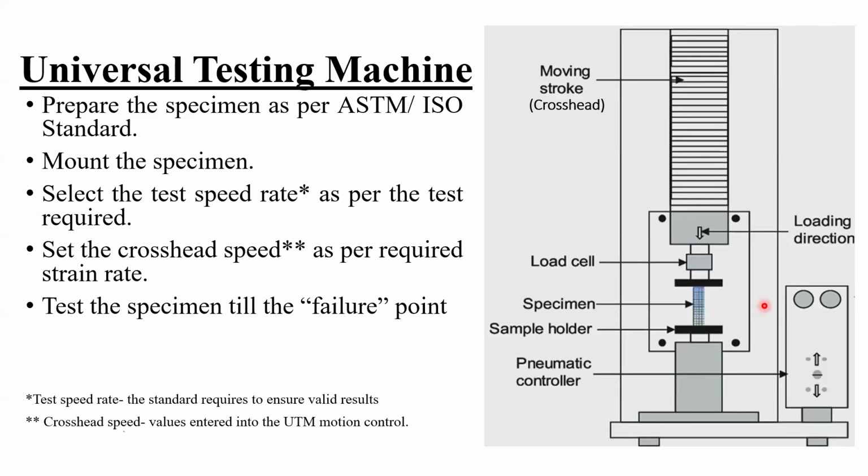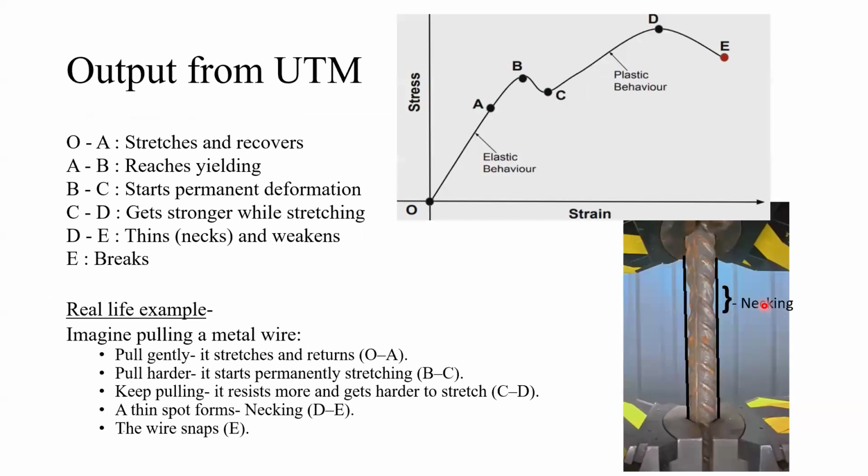I want to apply my pressure gradually. So 2 mm per second, or 5 mm per second, or also 2 mm per 10 seconds. I want to apply it gradually, so that a lesser tension is applied. You can change your crosshead speed as well. So you pull the material as a tensile test, or you compress it until it breaks or cracks. It will be recorded on the system.